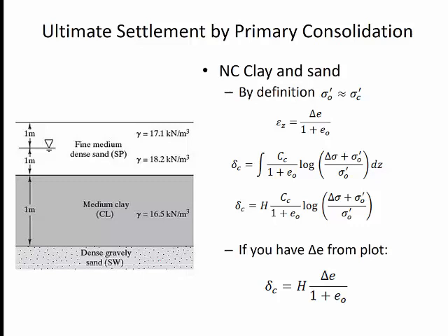If we perform a consolidation experiment on that clay material, we should get some information regarding whether it's been over consolidated or normally consolidated, and what the compression index and recompression index of that soil are. Then we can predict the amount of settlement that will occur depending on the amount of stress being applied at the surface. And that's what these equations represent.